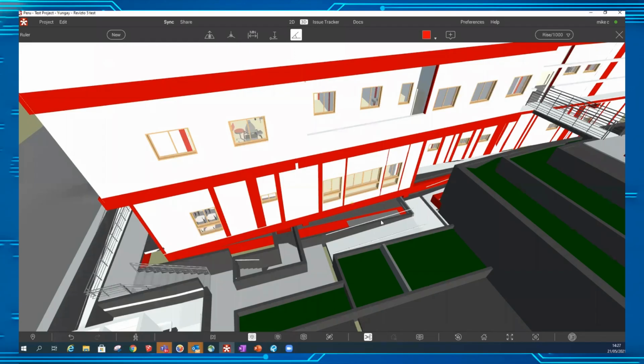A little yellow thing. If I put slope on there, that's telling me that's a slope of 98 in a 1,000. There's no slope there. 98, no slope. Yeah. So if you were looking at whether something was shallow enough gradient for someone in a wheelchair to be able to access part of the hospital or part of the school, then that can be a useful thing, just to quickly move it around and look for slopes.